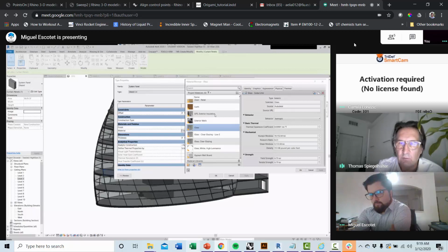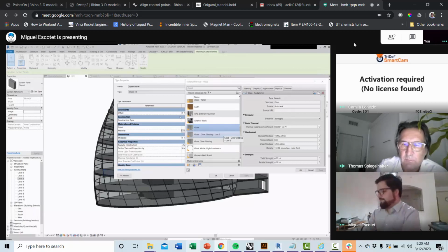So if you guys are doing a lighting analysis, daylight analysis, and this is an office, and you have selected the wrong glazing, right, Miguel? With the wrong properties, exactly. Then you have a huge problem to achieve the 500 lux on your desk plane.